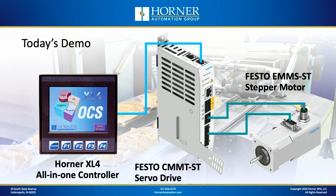Okay, so just a quick block diagram in terms of where the Horner OCS connects. Remember, the Horner OCS is an all-in-one controller, sometimes called a PLC plus HMI, that has built-in logic control with built-in I/O available, of course, a built-in screen, networking, all kinds of field bus functionality, and a lot more. And the interface to the servo is over Ethernet over Modbus TCP.